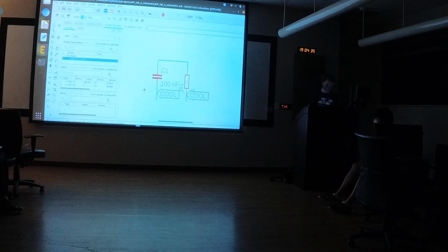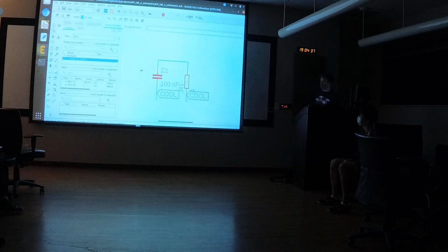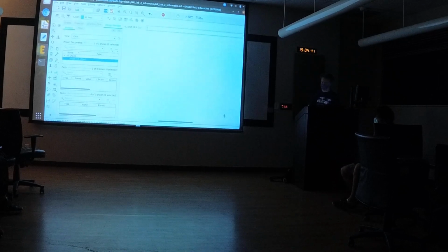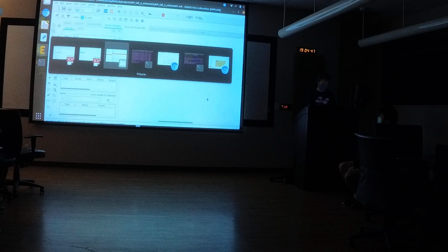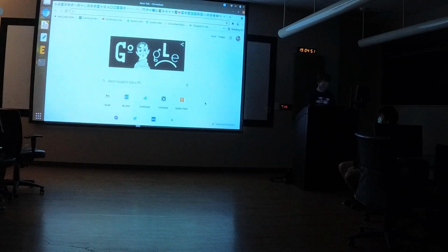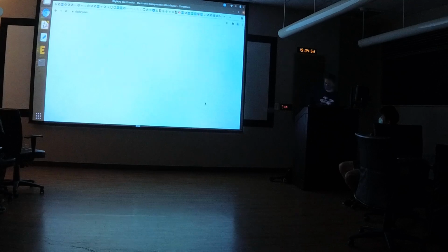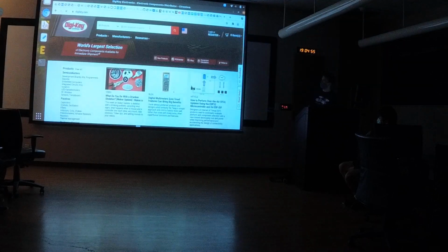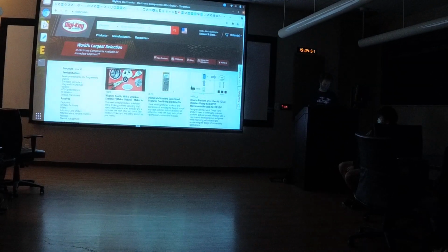Okay, well the move command doesn't work like how I expected. So this is all fine and good, but let's say you want to add the TPS63001, which is the voltage regulator I talked about before, and I'm going to give you a quick rundown of how to use it. Okay, we get rid of my email. We go to DigiKey. Okay, I kind of like DigiKey for looking at footprints because they have better footprint selection. We type in TPS63001.